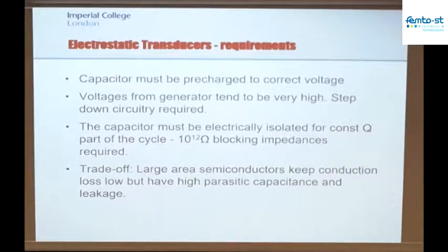You know, hopefully you remember that when you put a diode from forward conduction into reverse bias, it goes through a process called reverse recovery. It has stored charge in the PN junction when it's conducting in forward current, and in order to put it into reverse bias and stop it conducting, you need a small amount of reverse current flow to discharge the junction and to build up a blocking voltage.